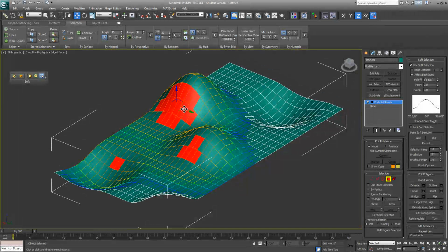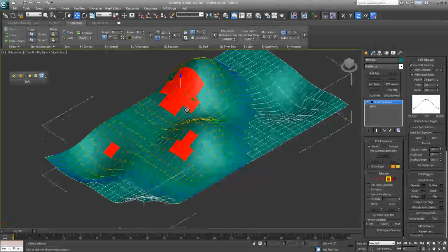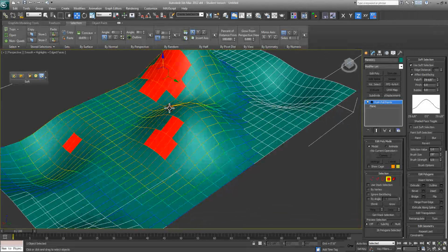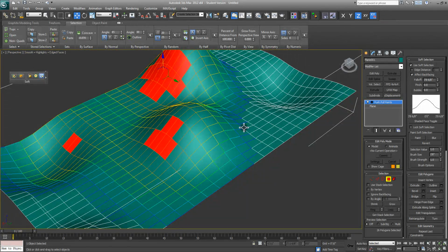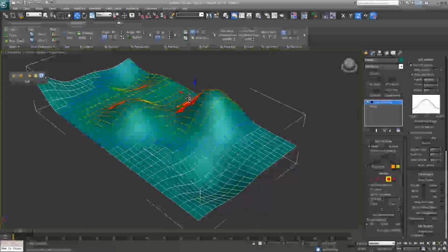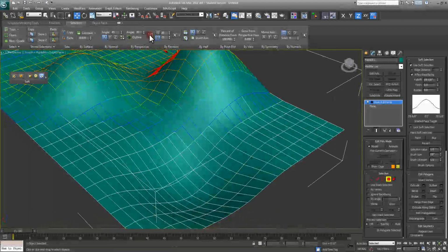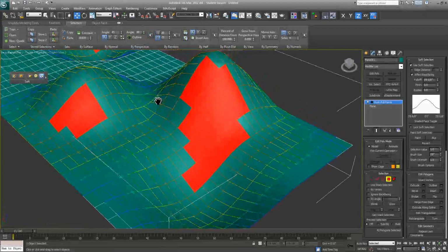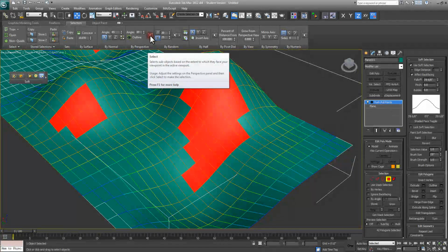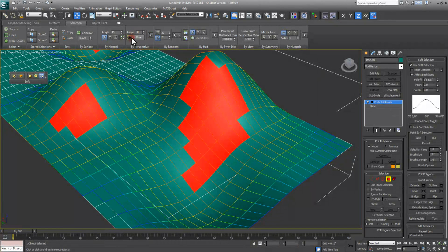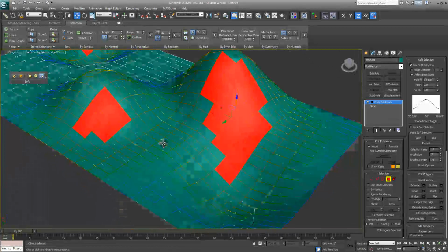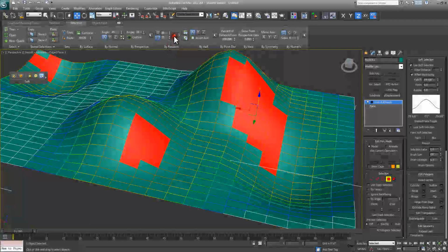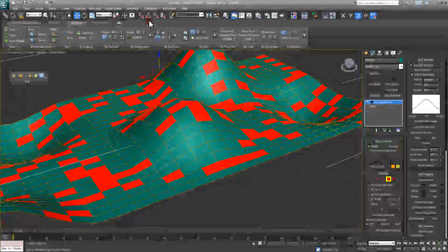The next thing you can actually do is by perspective, and this is all based on, so I'm going to hit P on the keyboard just to switch into perspective view instead of orthographic. And this is all based on your viewing angle. So if I click this button here, my little arrow, within 30 degrees of my viewing of this piece of geometry, it selects whatever is within 30 degrees of my viewing ratio.